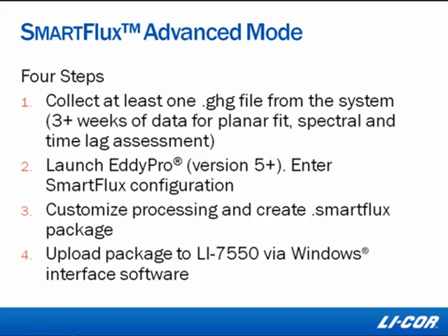So we take that file and we launch EddyPro. It needs to be version 5 or higher. And we go into the SmartFlux configuration. What EddyPro allows us to do with version 5 or higher is configure and choose our processing options. And that will allow us to create a SmartFlux package that contains our choices on how the data is processed and how data is screened.